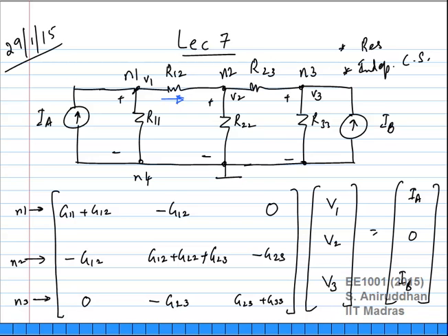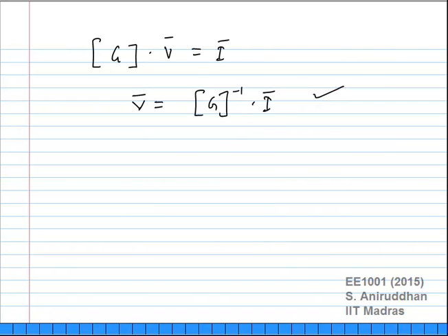You can write down these equations for all of those. Let's say I had thousands of current sources and resistors. You can write down these equations in matrix form, you can use a computer to invert this, right? And then get the solution. We know how to do inversion for 2 by 2 and 3 by 3. Beyond that, it will take a long time for us to do it by hand. Okay? But we have the option of using simulation tools to help with this. Okay, any questions on this particular technique so far for independent current sources and resistors?